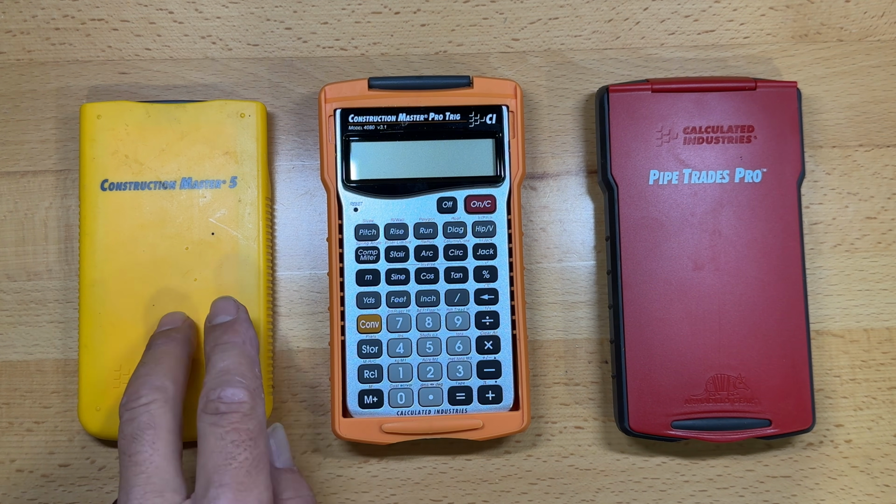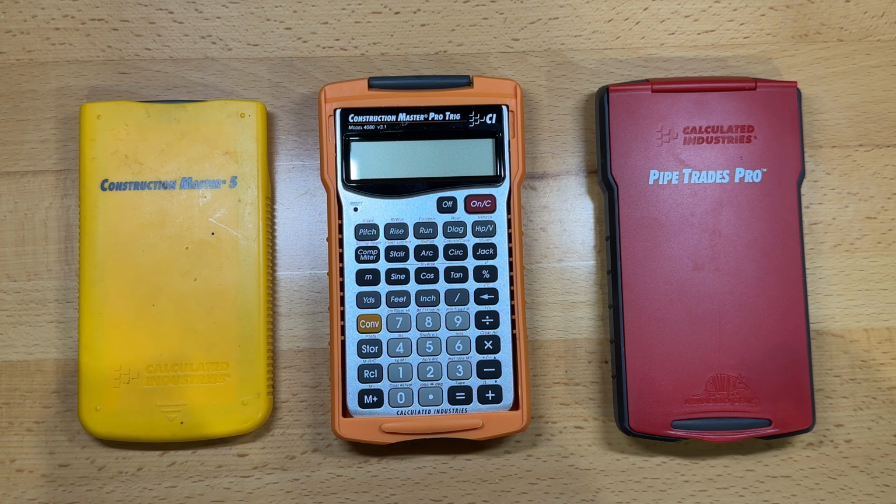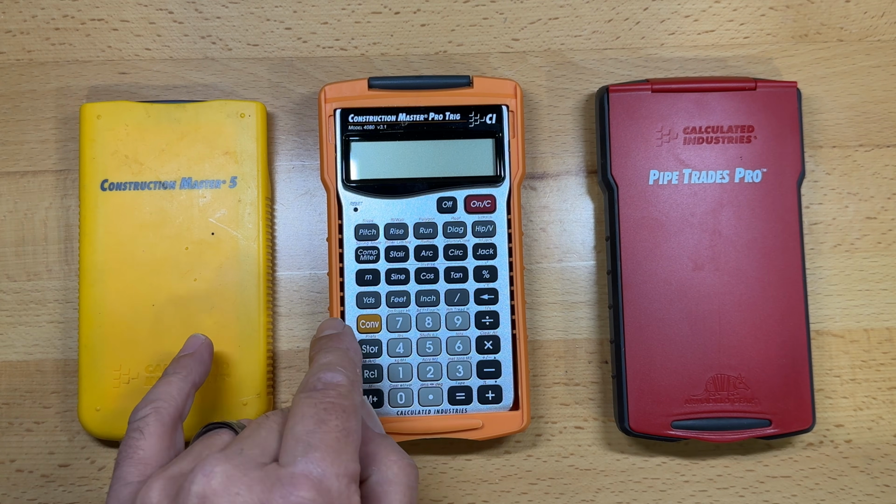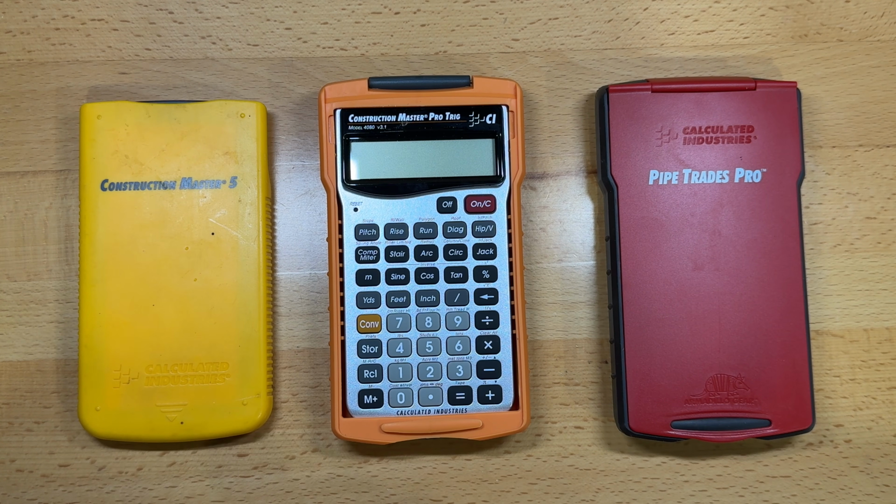But when it comes to these two in particular, they have one flaw when it comes to carpentry, and in particular when it comes to framers, and that is how it calculates jack rafters. Well, today I'm going to show you why the calculator is wrong, and then how you can make some different inputs in order to correct it so that it spits out the right numbers for you.